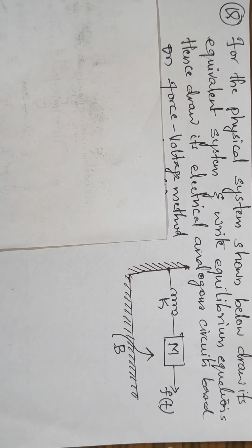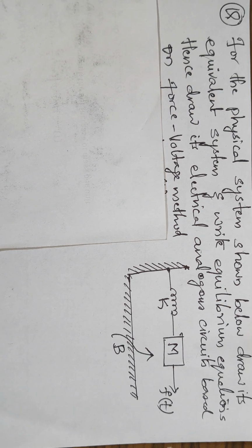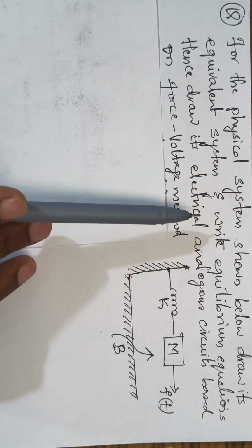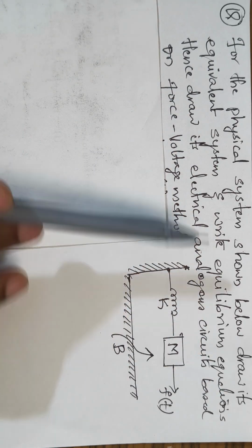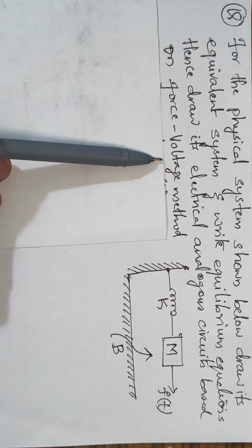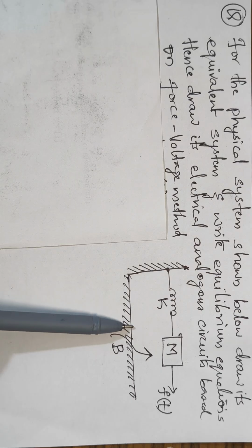In this lecture, we'll see a problem on analogous systems. So, the question is, for the physical system shown below, draw its equivalent system and write equilibrium equations, and hence draw its electrical analogous circuits based on force voltage method. So, this is the given physical system.